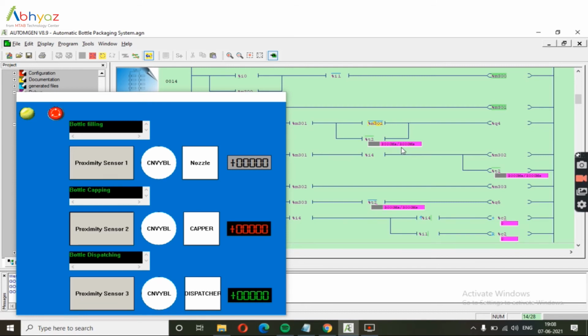After setting the timer, we have to start this system. After we place the bottle on the belt, which has a depression on it that acts as a holder to maintain the alignment of the bottle, when we trigger the proximity sensor, the timer starts and the belt stops, and the bottle is filled, and after it's done, the belt will continue.